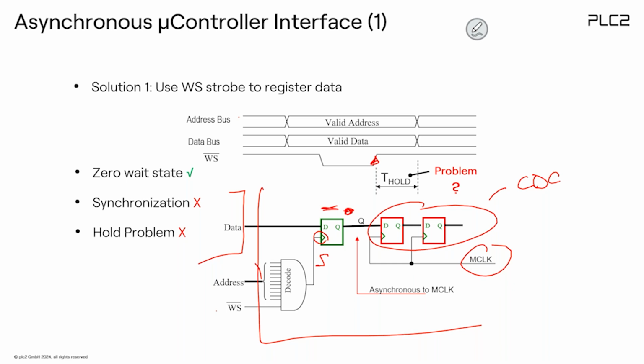But this application will work maybe in the functional simulation, but not in reality, because the problem is, you see, this would be a wide combinatorial function. Microcontrollers very often have a hold time of almost zero. This means even if you have a wide function, it takes some time to decode the rising edge or the write slope. The decoded pulse might be somewhere here, and we are missing the proper data because of the hold time requirement. So that's not very good.